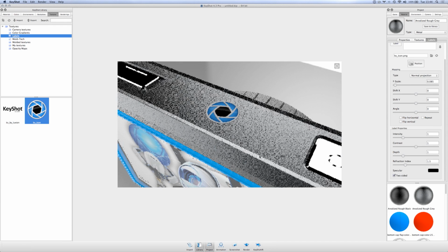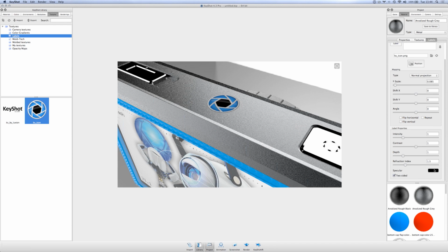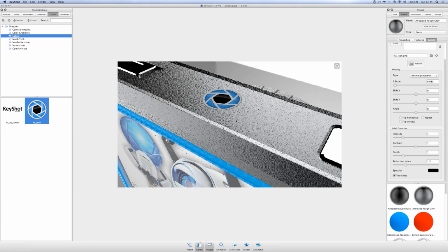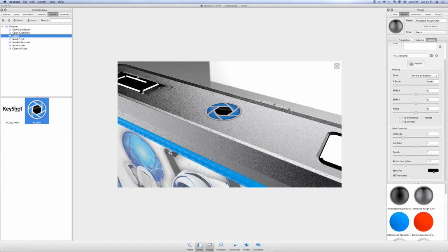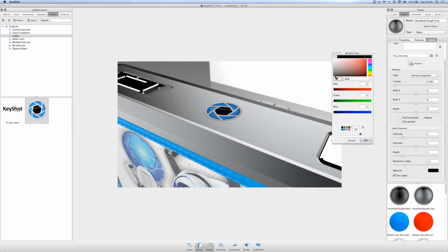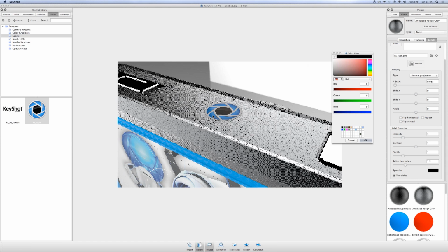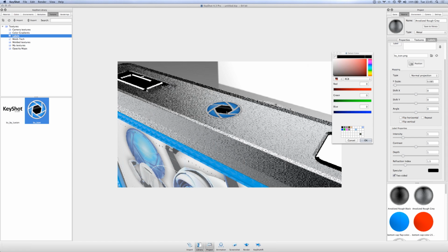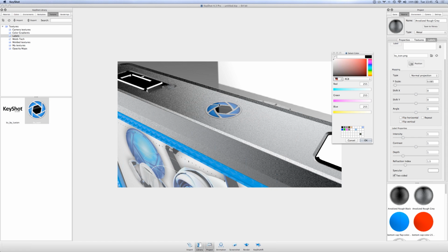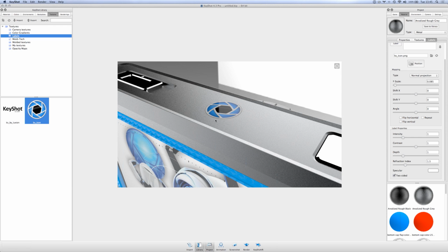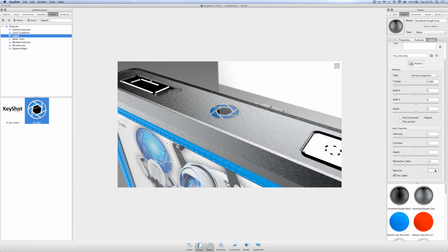I also want to make sure to call out that, again, we have this specular, this mystical specular, right? So all labels come in diffuse. But if I change the specular value, so right now it's not reflecting any light, but if I change that to white, now you can see I'm actually getting a shiny label. So I'll change that back to black. You can see it's totally diffuse, right? Now when I change that to white, I'm getting that crisp highlight on that label. So you can always make your labels reflective just by changing that specular value.